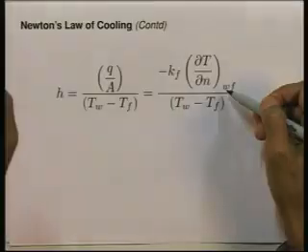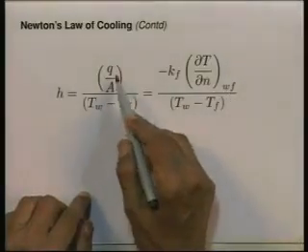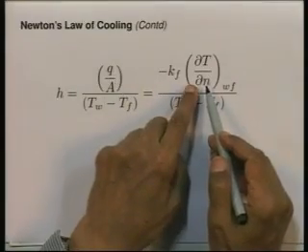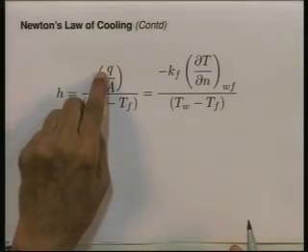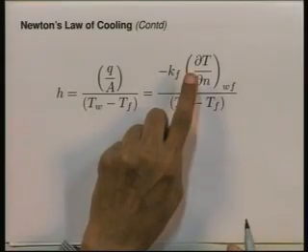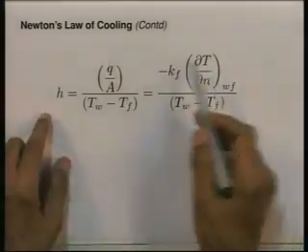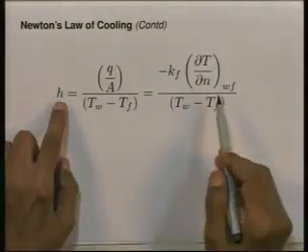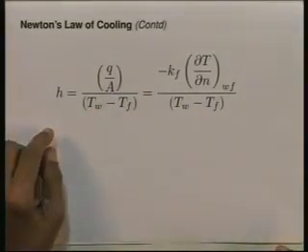So, we are using for the numerator now Fourier's law of heat conduction, because we know that right at the wall pure conduction is taking place, the fluid is stationary. So, the numerator, which stands for the heat flux by convection, can be converted to this expression by applying Fourier's law of heat conduction at the wall, and we get therefore this alternative definition of the heat transfer coefficient, or an alternative statement of Newton's law of cooling.